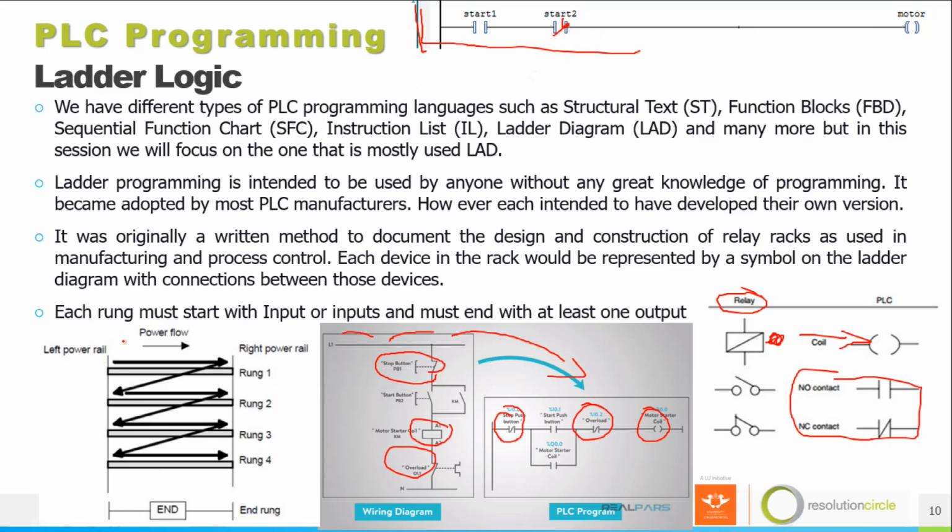So building a PLC ladder, you'll have a line on your left which will represent your power or your positive section. Then on your right you'll have your negative. So power, or current, will flow from positive to negative.